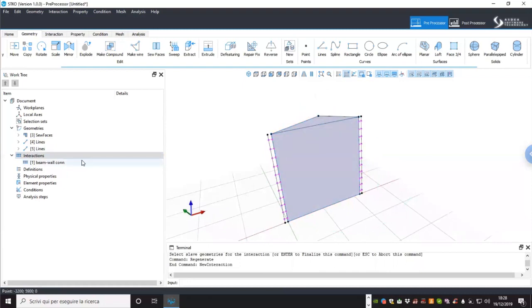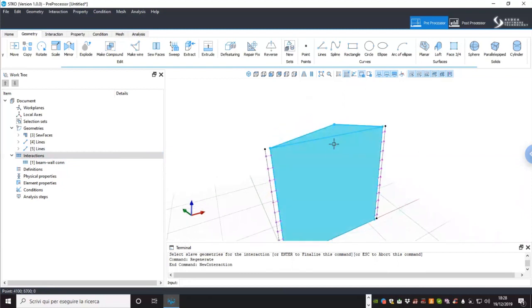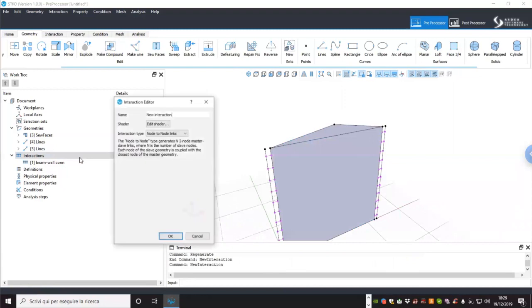Now we are going to create an extra interaction, because as I told you, here we want to create a shear wall. Now, how do we create a shear wall? Well, in this case, the model will be a shell, so we can just fix the rotation of this point. But in cases, for example, when you're doing a solid modeling, you cannot fix a rotation, so we can proceed in a different way. We can create another interaction that can be used to use an equal DOF constraint for the vertical displacement so that the model doesn't rotate. So once again, let's call it fix rotation.